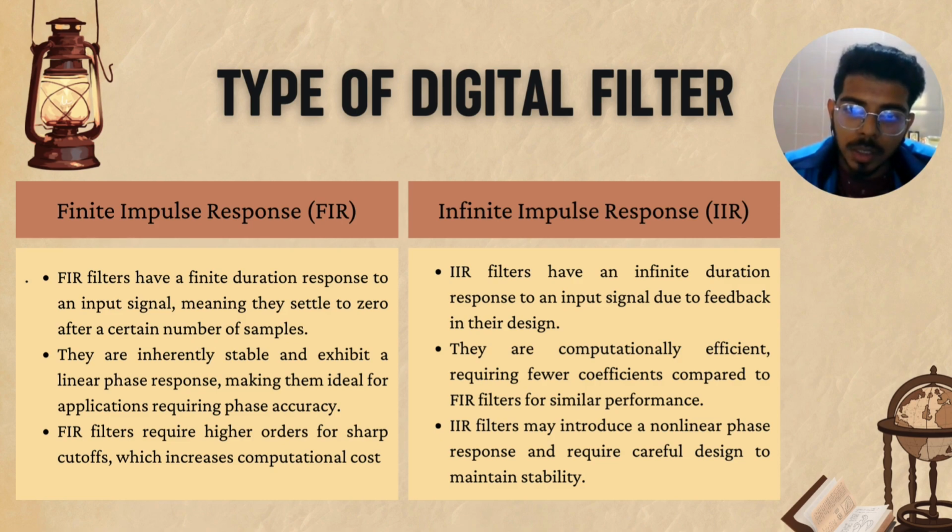Then they are inherently stable and exhibit a linear phase response, making them ideal for applications requiring phase accuracy. Also, FIR filters require higher orders for sharp cutoffs, which increases computational costs.